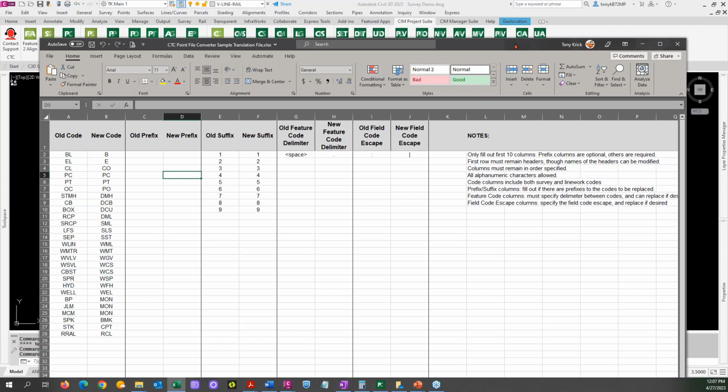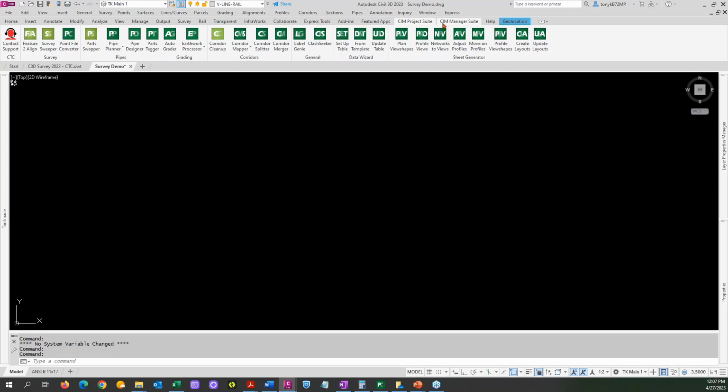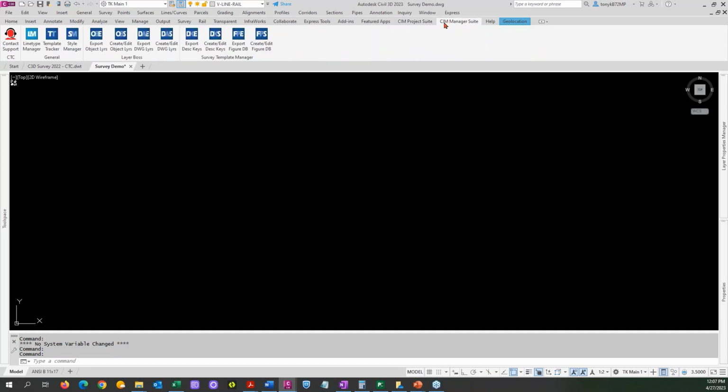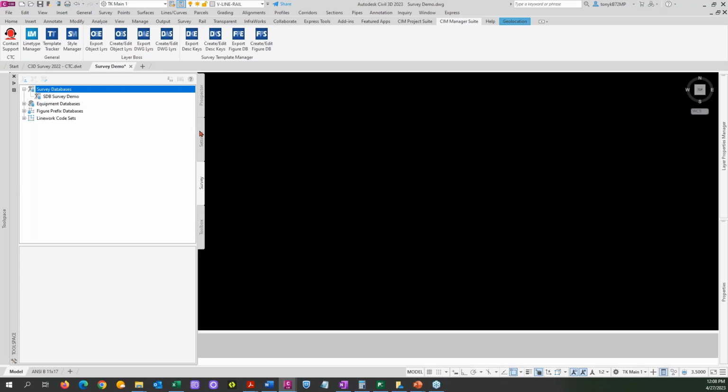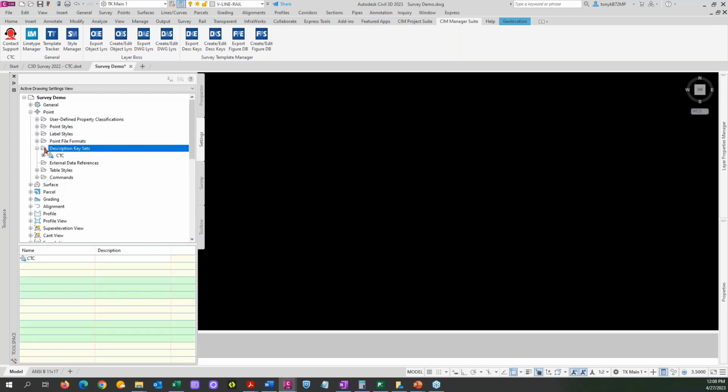But let's say you are starting from scratch. So let me just minimize that real quick. If you're starting from scratch, you have your description key set. And with CIM Manager Suite, we have export code sets here. So you can get it from here to your description key set, however you want to get it out of there.